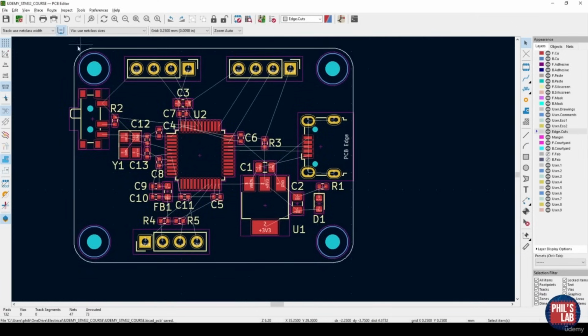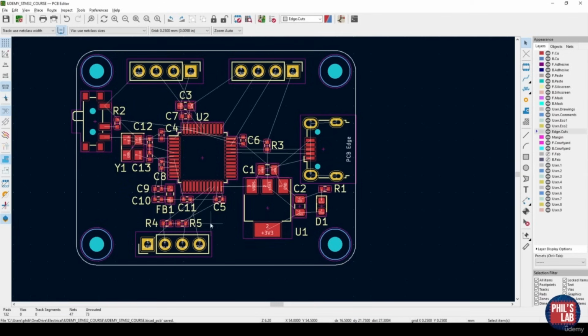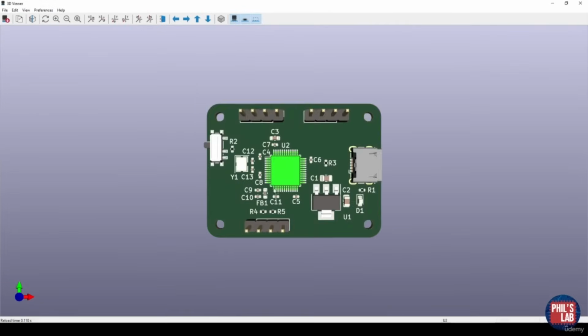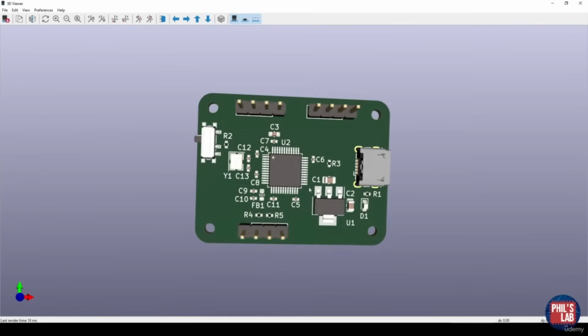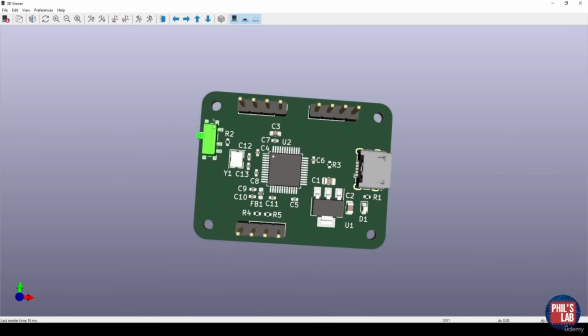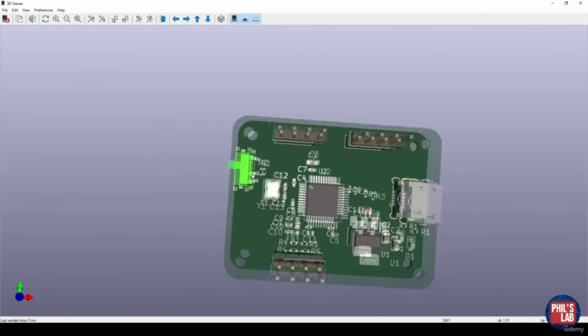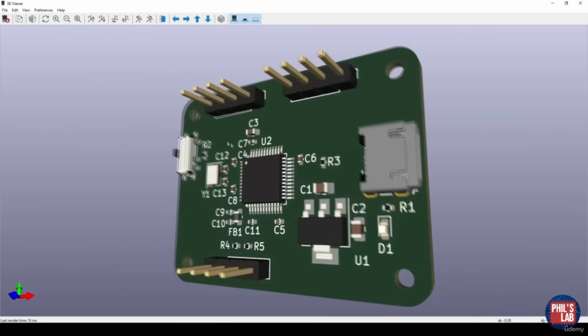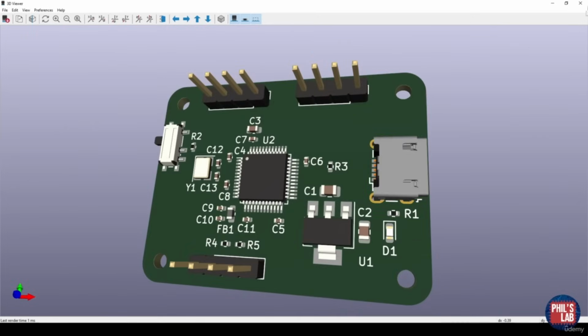And here we go, I've filled in the remaining corners, and because we have joined up this edge cuts layer, we can press Alt-3 and we should see our new board outline like so. Pretty nice, we have a defined board outline which has proper dimensions, proper distances between mounting holes, and rounded corners. Now we want to maybe move these connectors out a bit to make sure they actually fit with this board. So let me just do that now.